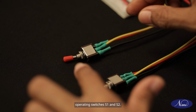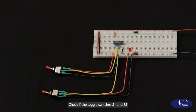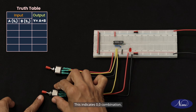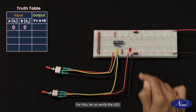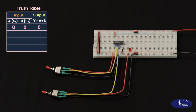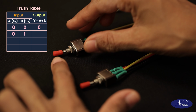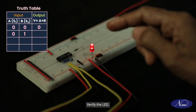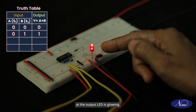Begin the test by operating switches S1 and S2. Check if the toggle switches S1 and S2 are in the low state. This indicates 0-0 combination. For this, let us verify the LED. It is not glowing. Now toggle the switches to 0-1 combination. Verify the LED. You may observe now that at the output, LED is glowing.